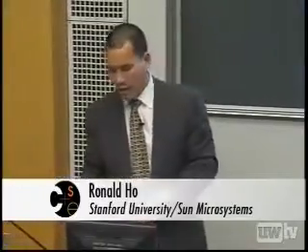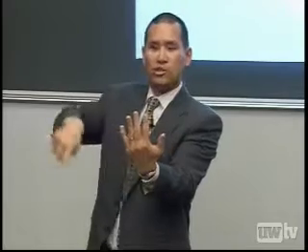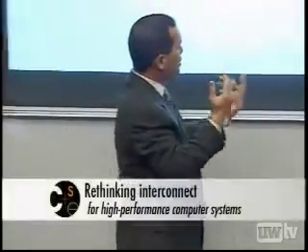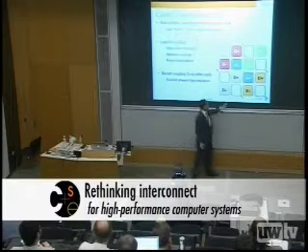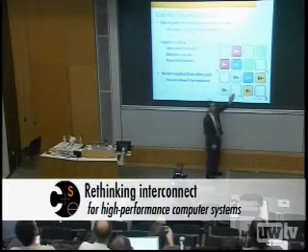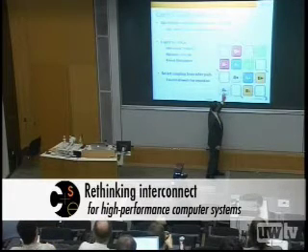What about separation misalignment, or Z separation, or tilt, or yaw? Well, to do that, layout helps you. Imagine that I've got 2 chips, and if I pull them apart, the problem really is that one chip can no longer see the matching pad on the other chip as clearly. Instead, you get defocused and you see all the pads around that other chip. That's crosstalk. Now, if I do my pads differentially, so I have A and A bar, and I arrange them in this sort of butterfly-styled layout, then I'll argue that separation of the chips is not that big a deal, or it's mitigated by this layout because I can make any kind of coupling common mode, no longer differential mode.